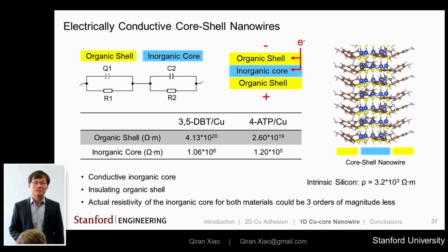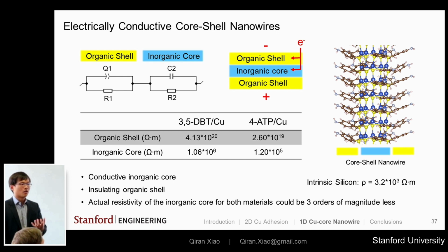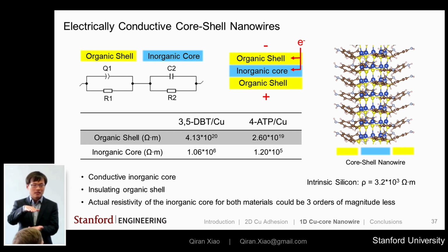Note, however, these numbers cannot be compared directly with the resistivity of other material, because both the grain size and their orientation profoundly change the measured resistance. And note that our nanowire, when we measure it, is completely randomly oriented in between our electrochemical plates, with many nanowires that are parallel to the plates, which will have absolutely no use in conducting electricity across. And therefore, this will result in a measured resistance for our nanowires to be orders of magnitude higher than if we measure directly from the two ends of a highly aligned nanowire array.